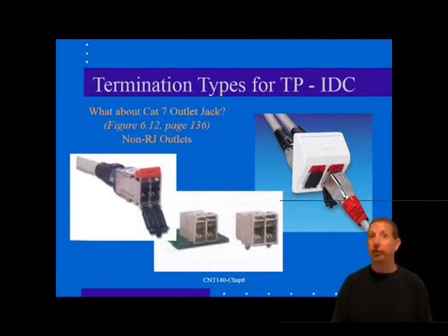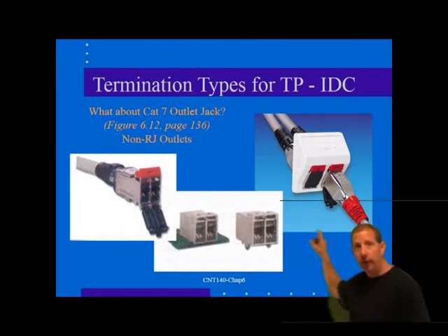So new non-modular connectors, for lack of a better name, have been developed that are much better at maintaining impedance matching and shielding in a very high-speed data link. These connectors support the new Cat 7 cables with the individually screened balanced pairs and avoid all of the sins of the RJ45 while maintaining a similar profile for snap-in jacks and snap-lock connections. An example of a high-performance Cat 7 non-modular connector is shown here behind me.